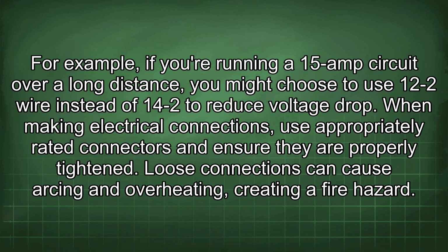For example, if you're running a 15 amp circuit over a long distance, you might choose to use 12-2 wire instead of 14-2 to reduce voltage drop. When making electrical connections, use appropriately rated connectors and ensure they are properly tightened.